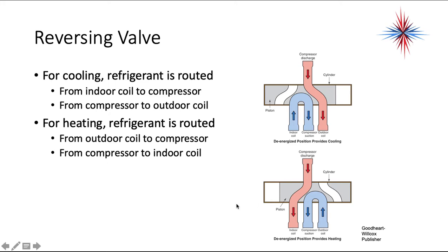Now be very careful about this, because sometimes de-energized is no longer cooling. So make very sure you understand when you're connecting the wires. Is it energized for cooling or de-energized for cooling? Most often, if you have an O terminal on the condensing unit or on the outdoor unit, it means that it's energized for cooling. The de-energized position is heating.